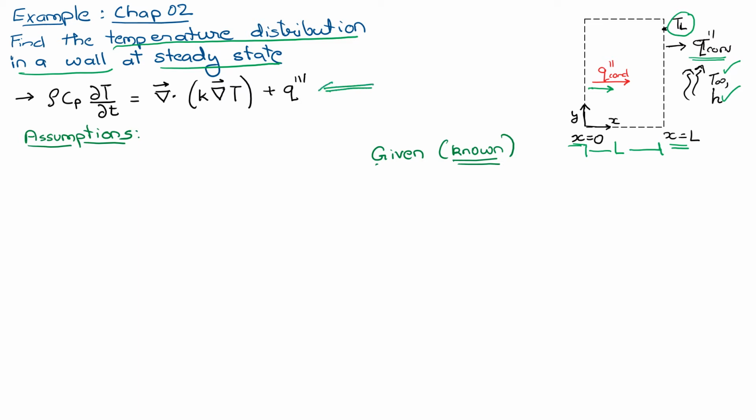So this is the heat diffusion equation that we had derived, and we can write this either in a 3D space or in a 1D space, and we've seen how the equations look. So whenever you start doing a problem, the first thing that you must do is write down the assumptions. So our first assumption in this problem is that this is a one-dimensional heat transfer problem. So your heat is just flowing in the x direction.